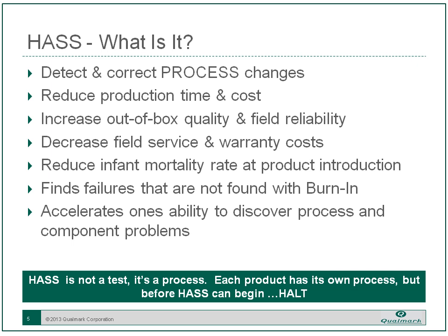So, a brief discussion. What is HASS? What are we trying to do with a highly accelerated stress screen? Really, a primary focus here is we're detecting and correcting process changes. There's two places where you can make mistakes in a product. You can design in something, or you can have something happen after your design is finalized. And HASS is intended to address that second portion. Find things that have changed in the process or in components that can compromise reliability.